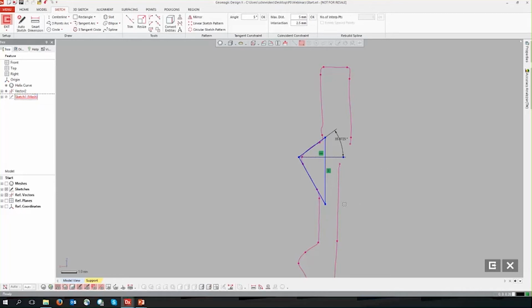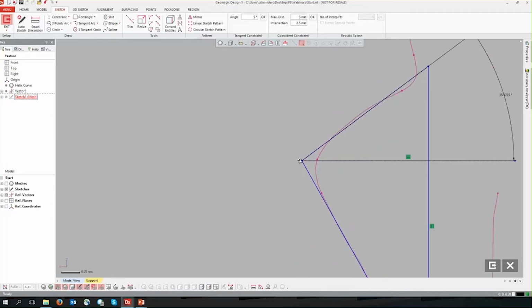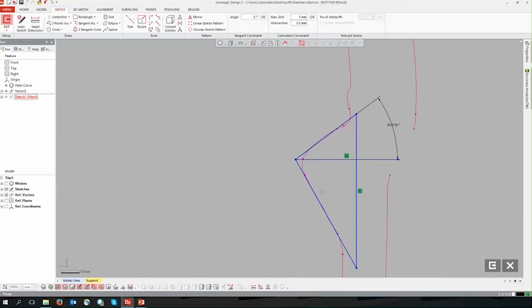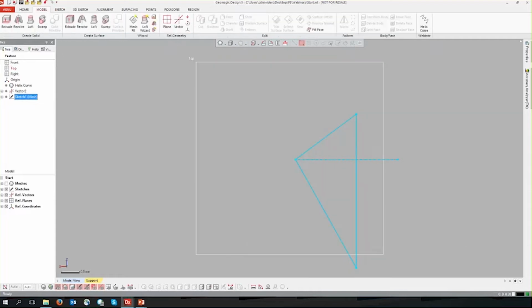So the main point to do at this step, though, to construct the helix is one, make the shape that will end up sweeping, so this will be the thread shape, as well as make the point where we're going to start our helix. On this part, we have our starting point slightly off the end of our thread where we cross-sectioned it, and maybe there was a fillet in the original drawing, or this part was worn down, right? So instead of having to make that 3D reference point, we're just going to extract and take this center point as our starting point.